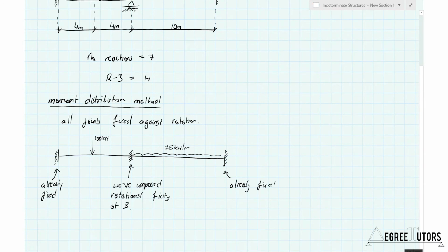So now look at this structure, right? The loading, let's just label it up, A, B, C, D. Right, the loading on AB is now completely isolated from the loading on BC and vice versa. Okay, so what we essentially have is like having two separate beams that just happen to be slid up and pushed against each other at joint B.